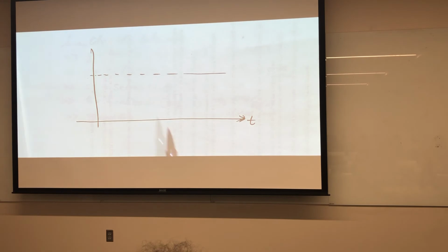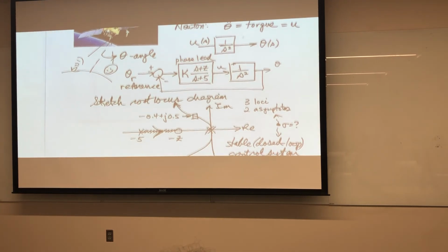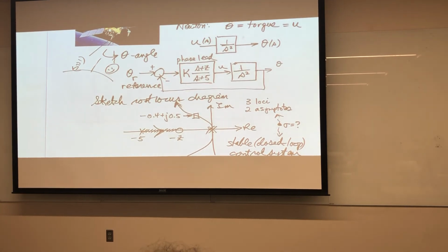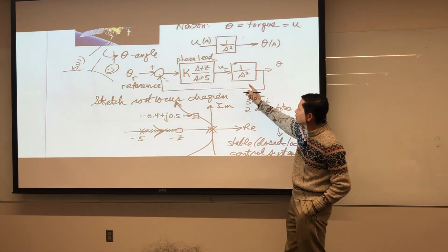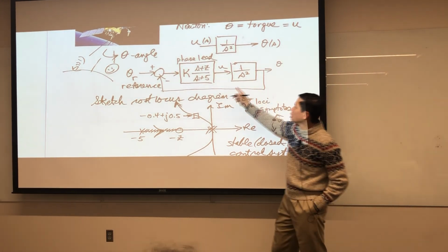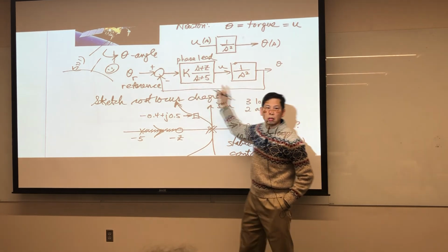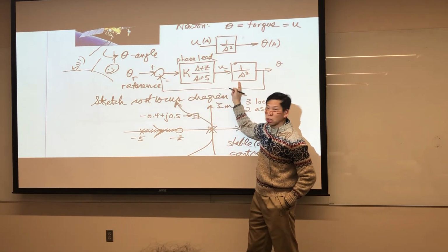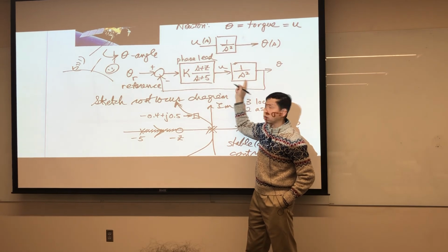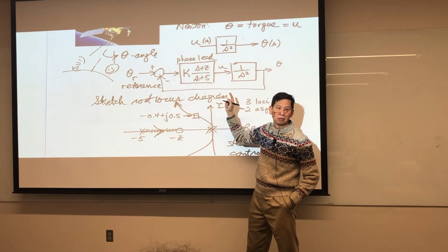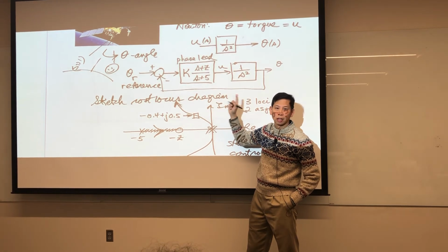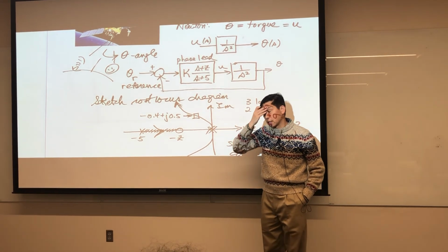Let's figure out where it's going to settle out, okay? Let's take a look at this control system, to review something from maybe the second test. Here's a control system. It's third order, because it's second order and first order, it's third order. What is its system type? It's type 2. And then we say steady state error.